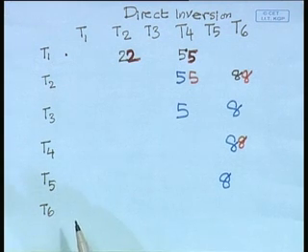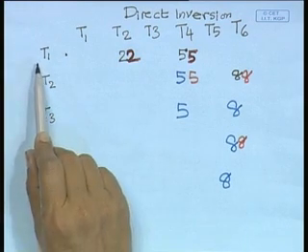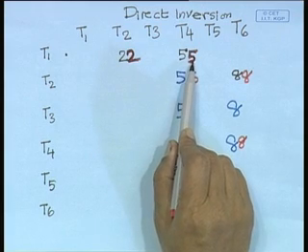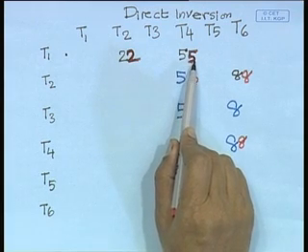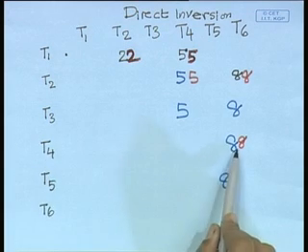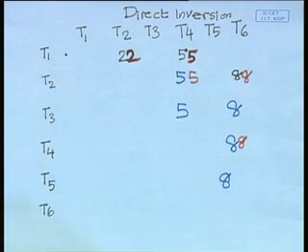Now, a task, as we had seen, can undergo at most one inversion, so we look through each row and find the maximum duration. For T1, 5 is the maximum duration for which it can undergo inversion, T2 for 8, T3 for 8, T4 for 8, T5 for 8, T6 is 0, right. Okay, so let us proceed from here. Is this clear? How do we calculate the inversions?